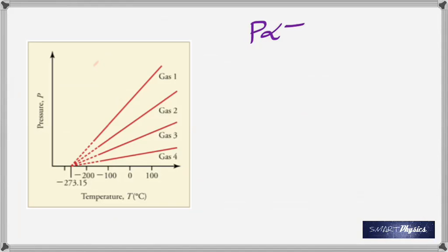Volume. So when the volume and the fixed mass of gas, because there's no extra air going in or going out, if your tires are good, it's not leaking, you know what I mean? So for a fixed mass of gas at constant volume, pressure is directly proportional to the absolute temperature. I use the word absolute temperature. Did you hear me? That means it has to be in Kelvin. I mean, this makes sense. Increase the temperature, the pressure goes up. Correct?